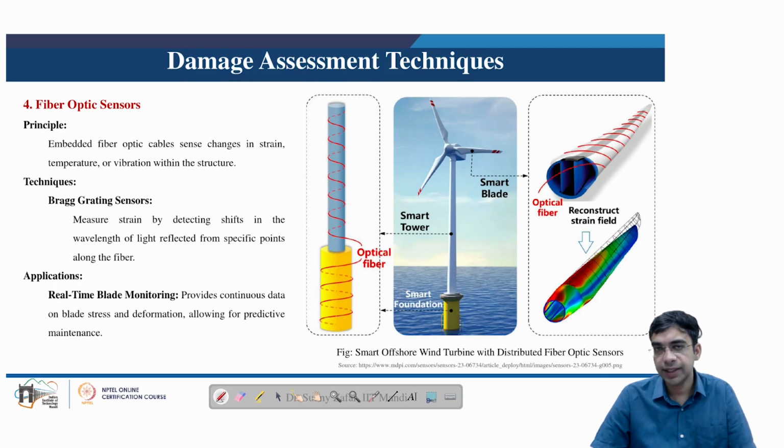Applications of this technique involve real-time blade monitoring, which can provide continuous data of blade stresses and deformation, allowing for predictive maintenance. So we can say that by use of optic sensors, we can develop smart blades which can provide continuous data, and continuous assessment of the health of the blade can be done.